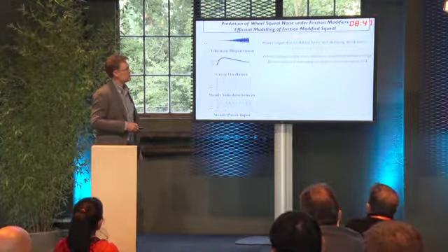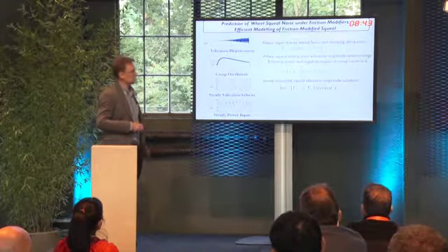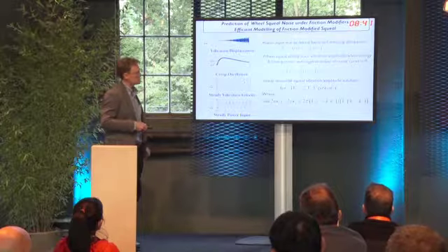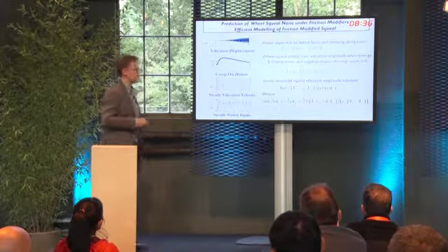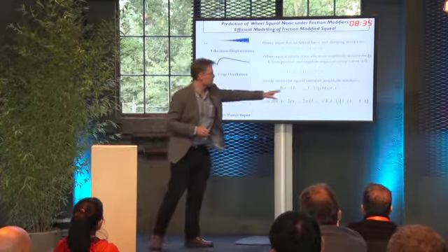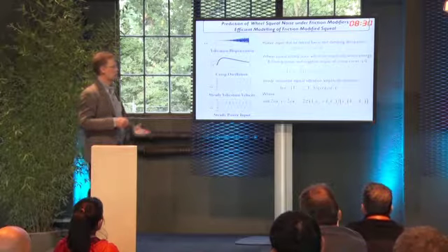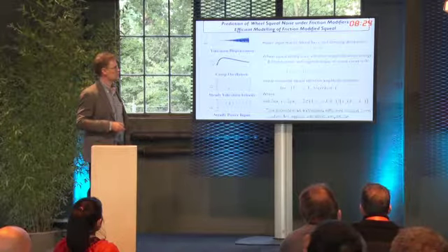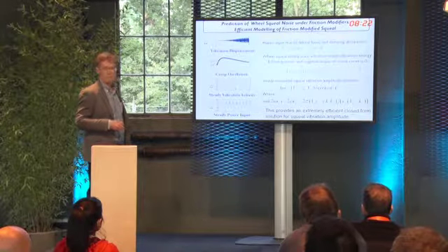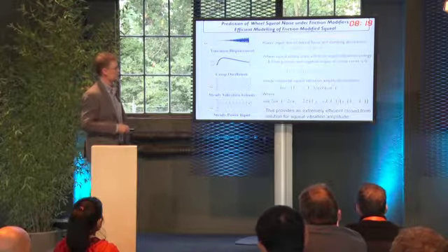I'll cut through the maths quickly, because it's just based on that energy balance, but based on that we fortunately came up with an analytical solution for this vibration amplitude as a function of those critical curving, lateral creep and modal dynamics parameters. And this is extremely efficient for us to look at a wide range of parameters.